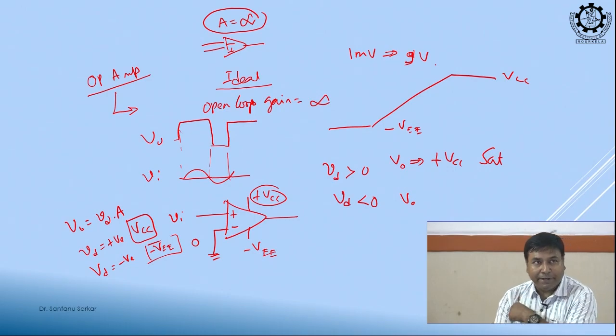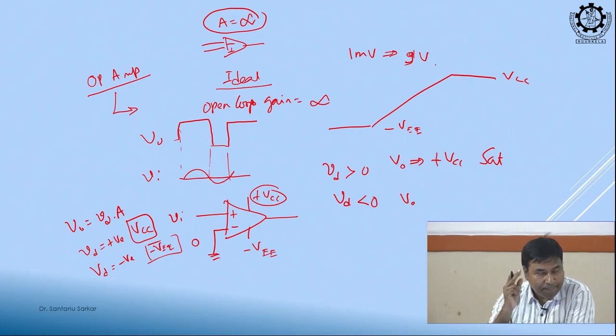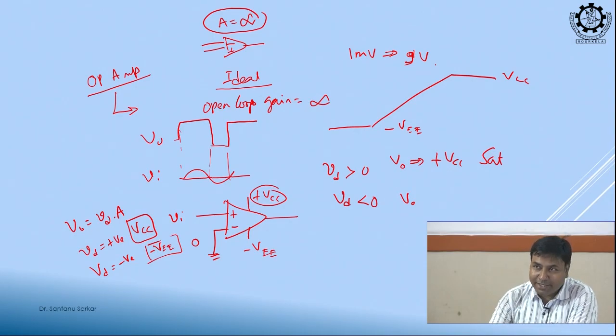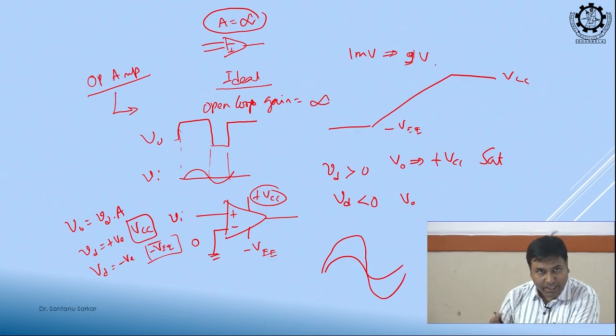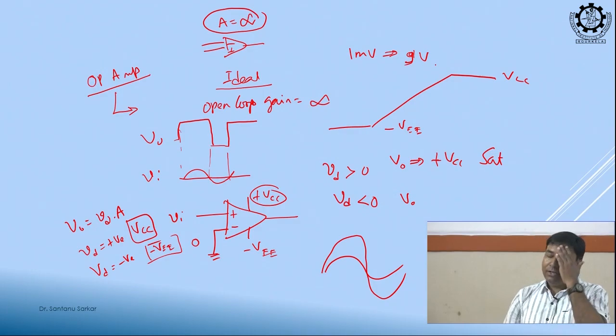But is it an amplifier? What is the first characteristic of an amplifier that we discussed? Linearity. It should look the same, right, but does it look the same? I have a sine wave, if I want to amplify it, the output should also be a sine wave, right. If it is not, then we say that other nonlinear elements are superimposed and distortion will come.